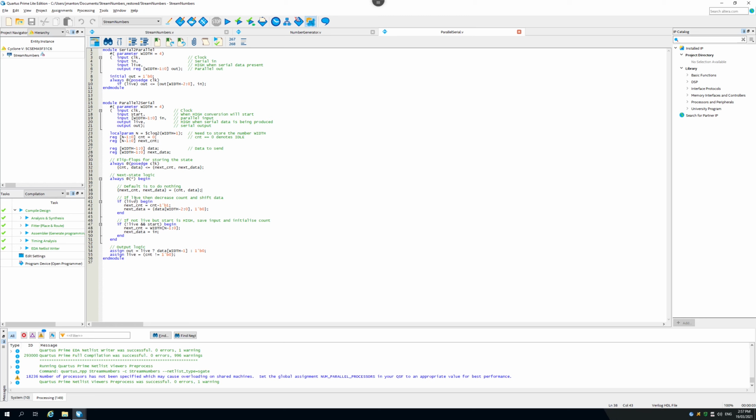If we're live, and live means that we're currently sending something, and live is defined down here, and that's fine because the order doesn't matter. I'll come to that later. If we're actually sending something, then our count is non-zero, and to move to the next state, we subtract 1 from count, because count tells us how many bits we have left to send. If there's another rising edge, we have 1 less bit to send, so the next count is 1 less.